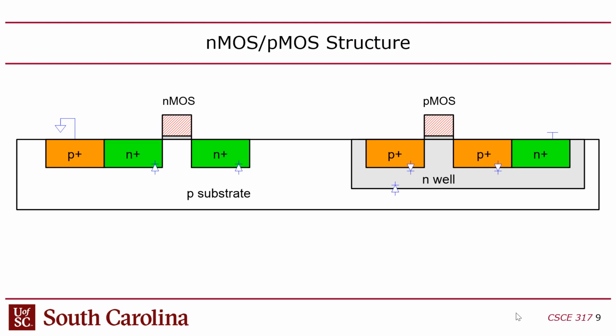So usually the way they set this up is, if you want to energize a substrate, you want to bring this N well up to VDD, it's done through a step where you first connect to an N plus diffusion area, which makes it easier to then inject into the N well that's less diffused. Same thing over here. The substrate has this P plus diffusion area that's used to increase the contact between the ground, which ultimately comes from a wire.